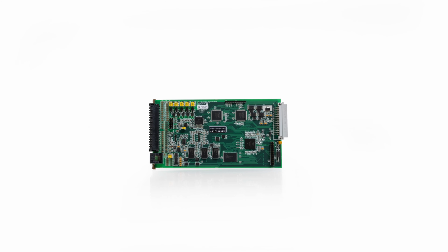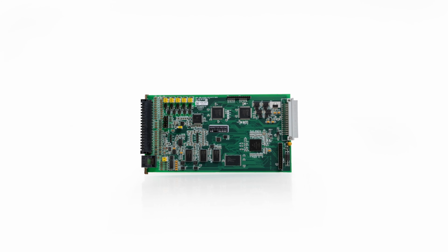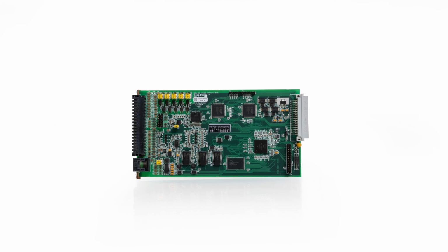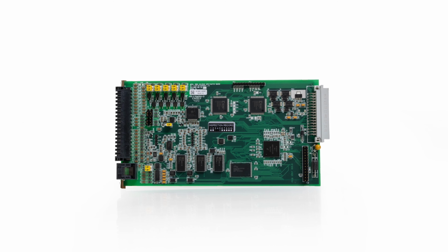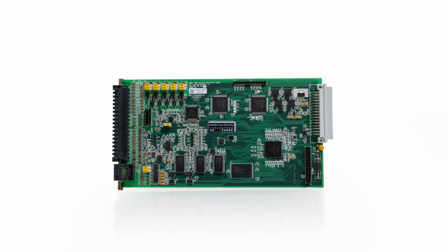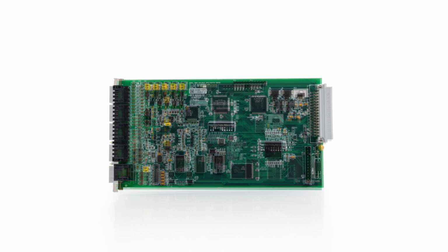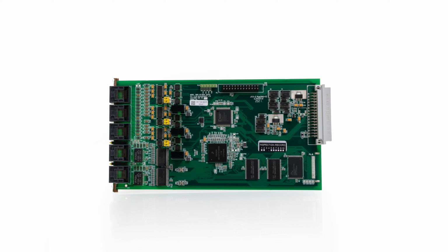The option boards can be divided into two types, input-output and communication. The input-output boards are used for measurements and results, outputs and control. Typically a system will have one input-output for each stream, although it is possible to have more than one stream per input-output board. For physical measurement it is usually required to have a board per stream. The communication boards allow for connection to a variety of other devices and systems, such as gas chromatographs, printers, supervisory computers, etc., via either serial or Ethernet connections.